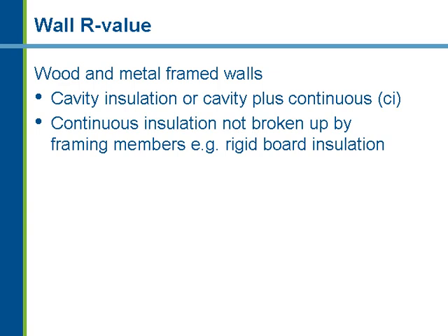Wood frame wall systems, except in Climate Zone 8, will only be required to have an R13 insulation, whereas in metal frame wall system, starting with 5 and Marine 4, will need both an R13 installed between framing and then an R3.8 continuous insulation. So there will be a little higher requirements for metal frame wall systems in colder climates. Warmer climates, though, an R13 will be pretty much required straight across the board.